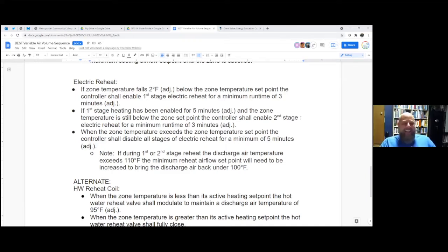We'll go ahead and table the conversation for right now. I am going to add on to answer Carlos' question specifically on CO2. Yes, CO2 sensors are currently one of the two primary types of sensors being used as an analysis factor for indoor air quality, for demand controlled ventilation. And VOC sensors are the other one that is currently written into some specifications.